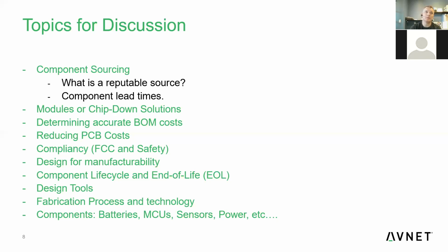As you scale to production, what you're going to find is you're going to start to move to more volume-based distributors like an Avnet, where those components are not going to be in inventory, and those components need to be manufactured before they're delivered to you. And that's when you become reliant on what we call component lead times. One area where we're seeing lead times get significantly pushed out, and they have been for some time now, is on passive components, in particular ceramic capacitors. And that's pretty applicable to anybody that's in Hardware Studio Connection.